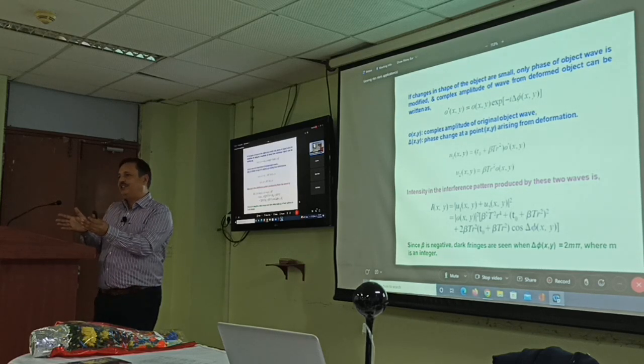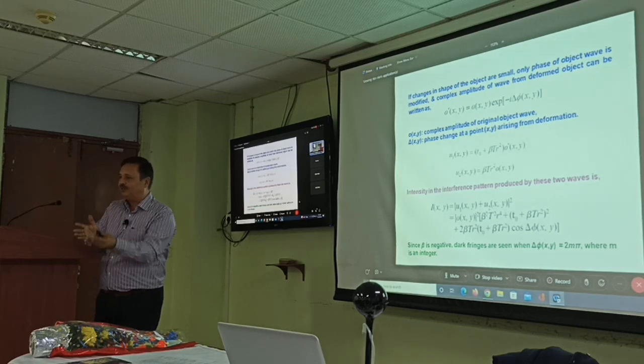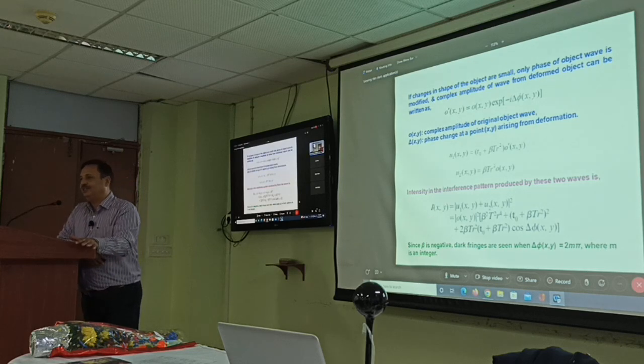So you have two states basically. One state not deformed, second state some deformation has happened. You have one interference pattern, you have another interference pattern, and then you can compare them. Once you compare them, then how much the deformation is, that you can measure.